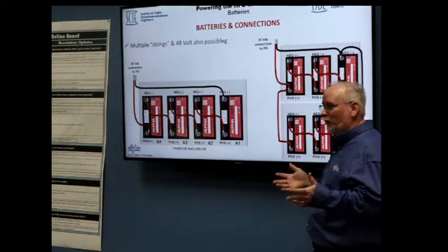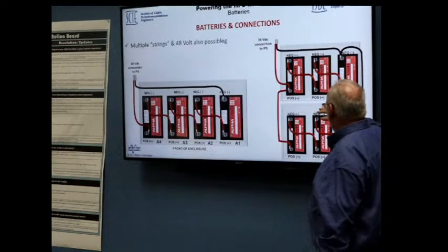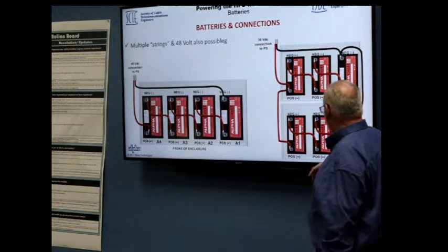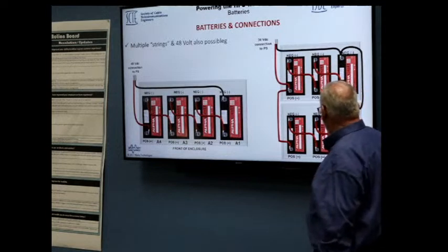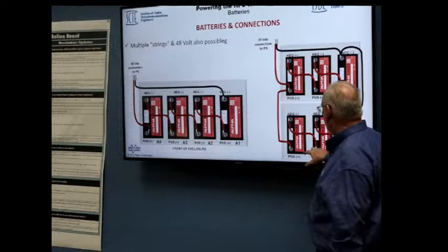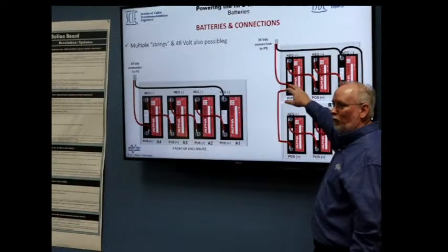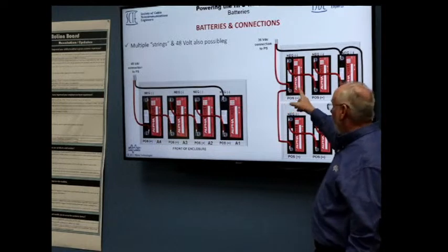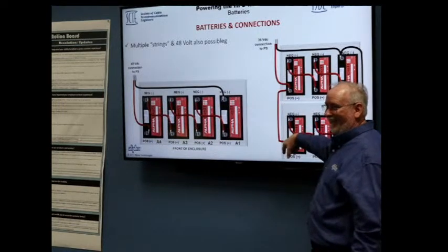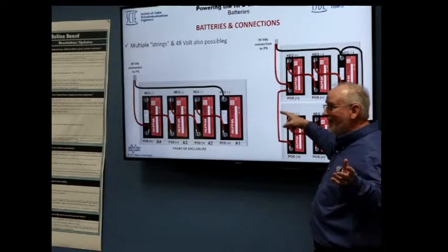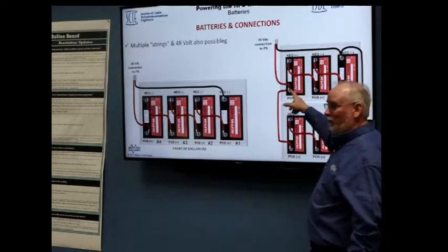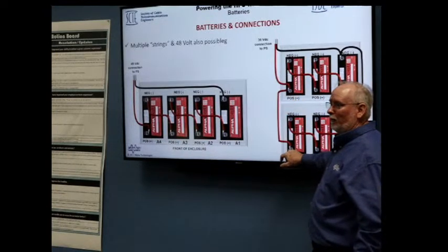4 connections makes sense. We go to the second set. All we need is battery 1 positive and battery 2 positive, because the battery 3 positive is actually measured at the same voltage as this one. So we assume that you've got a good connection here, okay? We sometimes are wrong, but overall we assume there's a connection here. That's why you don't need the third one.